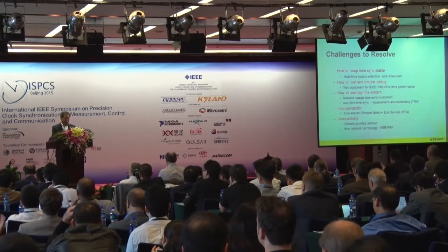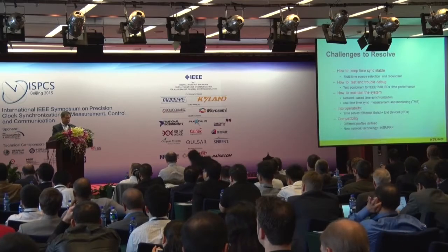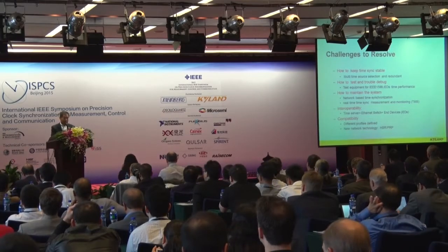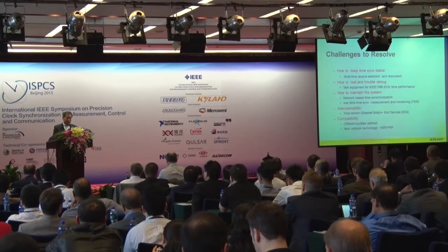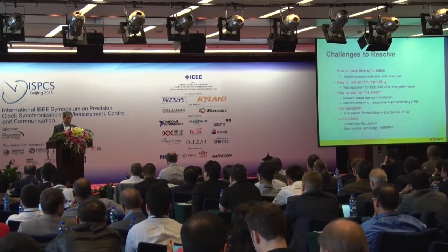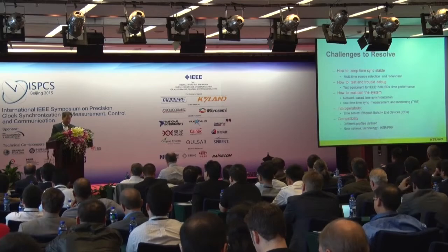Also in the substation, we must have interoperability among the time server, Ethernet switches and IEDs. We must keep all the IEDs time synchronized.